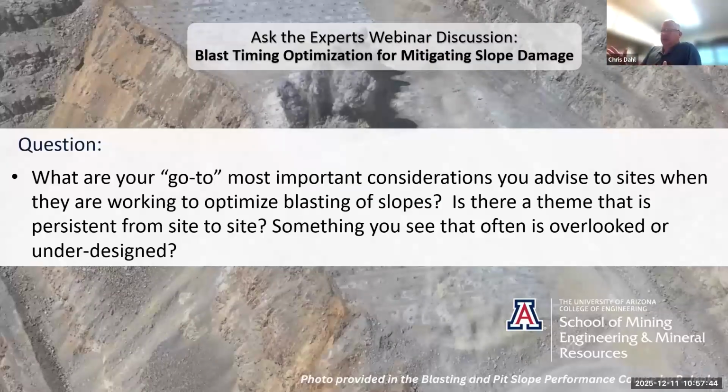And then from just a very high level, the energy triangle, the distribution of your explosives, the confinement, the energy levels, understanding cross-sectionally as we approach these slopes, we know that we need to reduce the energy levels and really need to understand that we still have, say, good distribution, if you will, via air decks or physical decks, multiple charges up a blast hole, for instance, depending on the application, the rock hardness, etc. So again, those would be my go-tos: signature hole methodology and good energy distribution and levels as you approach slopes. I guess further continuing on and turn it over to someone else.